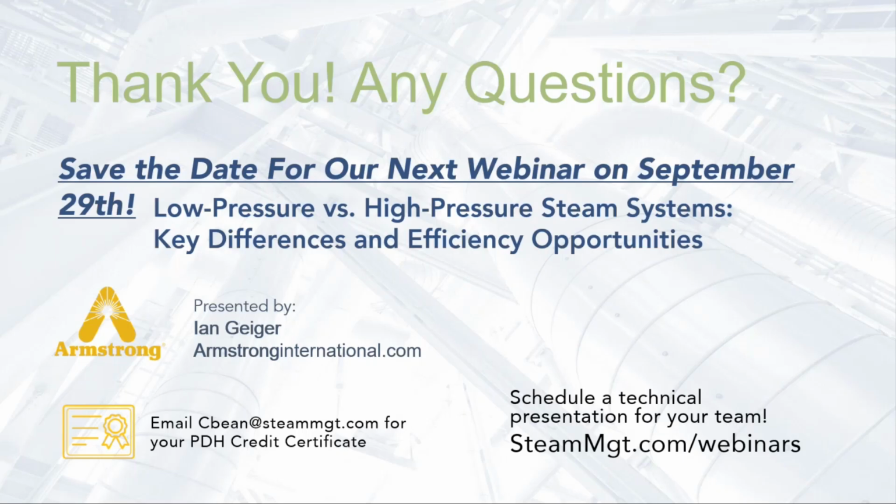They have a condensate tank that's just blowing steam, and traps are very difficult to access, and we can't even really isolate different zones of the system to identify where the trap failure or failures are. So that was a challenge, and that would have been a good place to have some monitors, even though I don't think the pressures were necessarily that high on those traps. But yeah, good point.